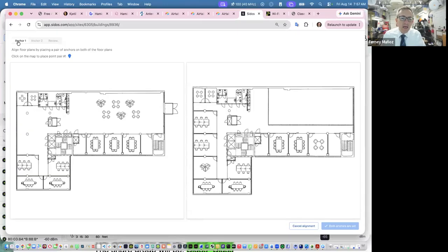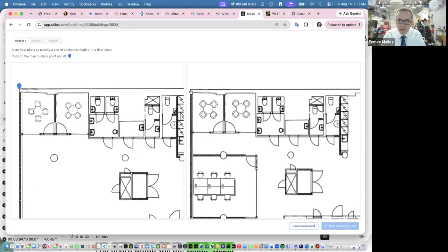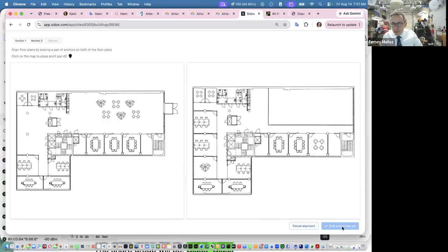The first alignment point, the first anchor, let's say I can zoom in, say this corner, click, notice it's blue, is the same as this corner in that place, okay? I'm just telling the software that point is on top of this point. And I say, yeah, those are good. Okay, now show me a second point where these floors meet.